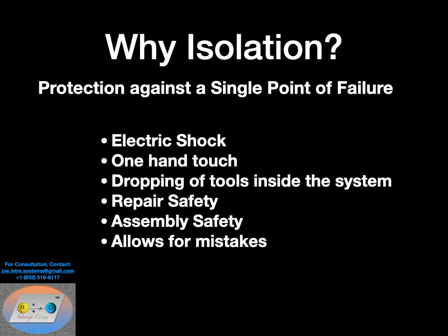Okay, so yes, we're dealing with high voltages, and if it's, say, a lithium battery system, you have high currents and low impedance, right? So you want to make the system safe for technicians and service engineers making mistakes, say dropping tools, torquing down a bus bar bolt and the wrench falls. You want to make it as safe as you can. And this isolation from ground is one way to do that.